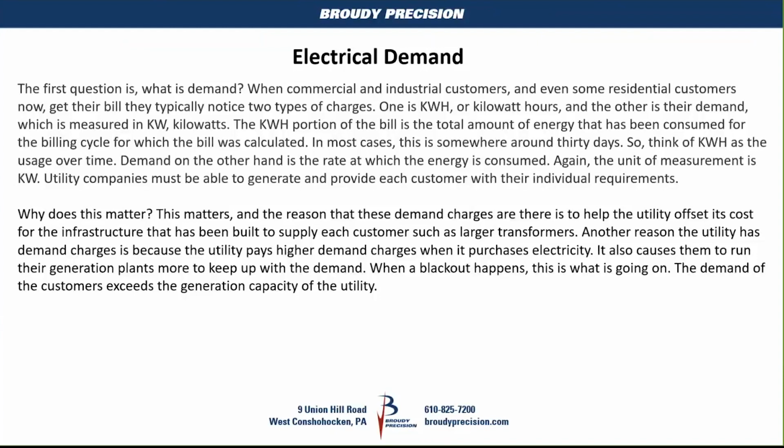Like in the summertime, we have these blackouts or brownouts that happen, and that is because the demand of the customers exceeds the generation capacity of the utility. Those are two reasons that the electrical demand rate is usually charged on commercial customers.